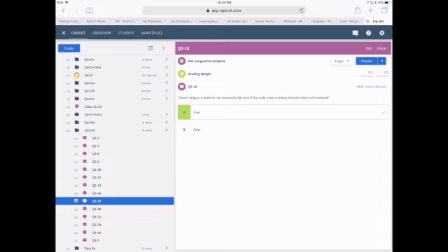Okay. There are some materials that have an endurance limit, but their yield stress still drops dramatically. So if I did increase the stress I applied into that range, I would still destroy the steel, but if I stay under that endurance limit, the material would not fail. So, fatigue is defined as a lower stress than the yield stress that can cause a material to fail once it's cycled enough times. Okay, so let's go back to here.